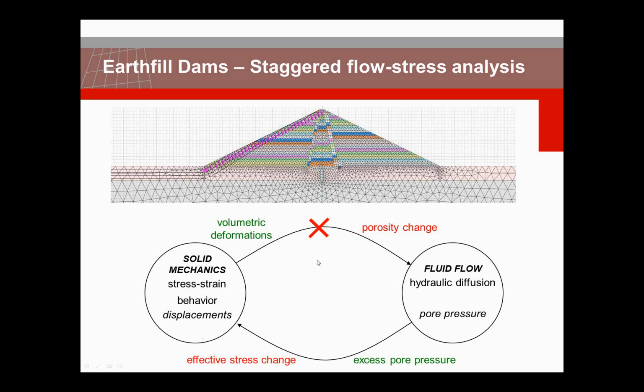In this type of analysis, the volumetric deformations, which would affect the porosity, are not considered. So this is a one-way coupling. And the type of dam here, the earthfill dam, uses very porous earth with a clay core that you see in the middle and a cut-off wall.